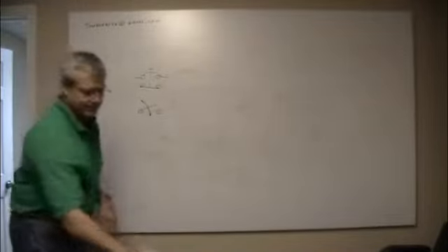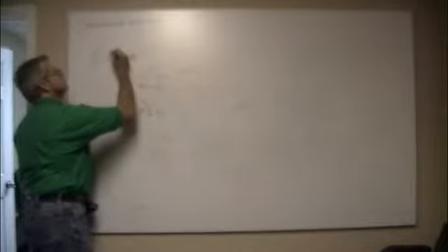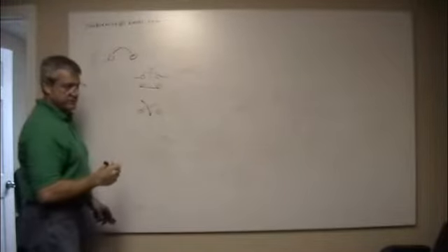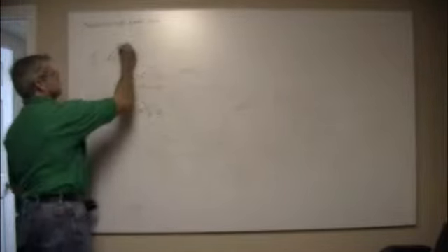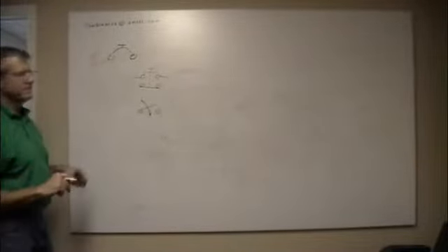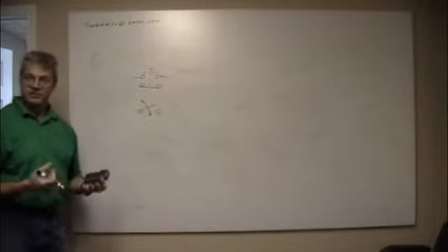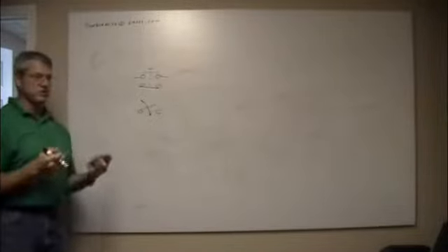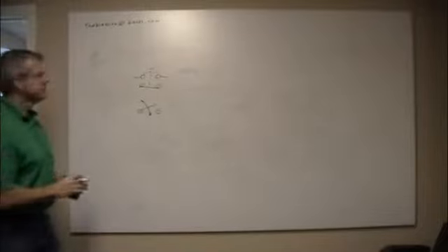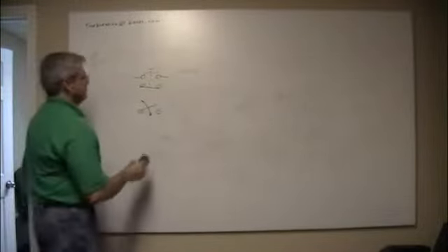And if you ever see one of these, well, let's see, that could be headphones, or it could be a circuit breaker. If it's got that, it's a circuit breaker. Which is a kind of a switch, but it's a thermally activated switch. What makes it pop is when you draw too much current, it heats up and pops loose. And then when it cools down, you can reset it and you're good to go.